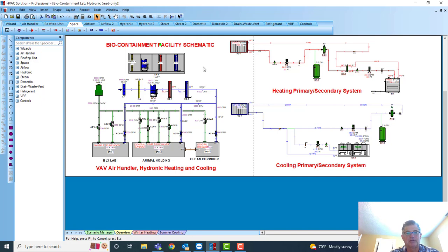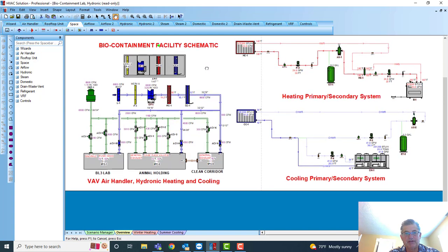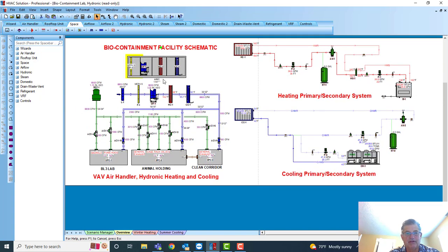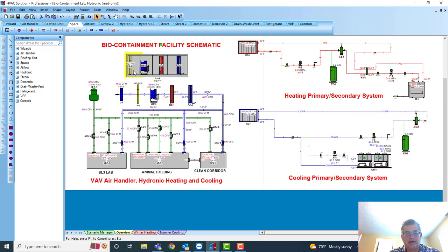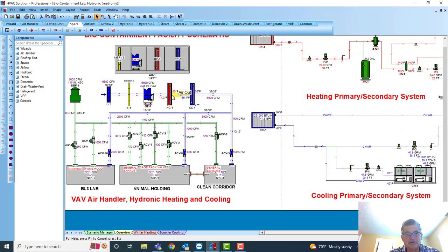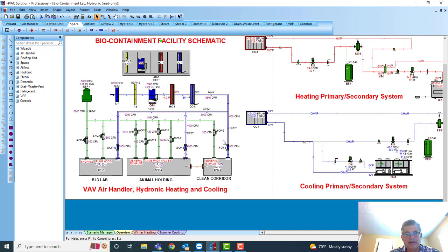These are projects we've done in our consulting engineering firm over the last 20 years. Typically, like all projects, we have an air handler that shows the coils and fans. Blue fan means it's an outside air fan. Then we have the airflow diagram showing how that air handler is hooked to a louver. There are the filters and coils in the air. You'll see temperatures in the airflow diagram down to spaces, and then you'll see the supply, like a Phoenix supply valve, and then the exhaust valves there.